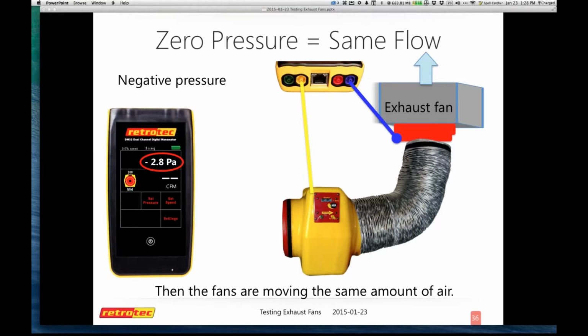John is asking, what would the tap look like inside of the flange or inside the duct? One of the methods that I use, I don't have a picture of it, maybe I may have one coming up, is I use some kind of sticky Velcro, and then I actually put the tube in, and then I put the other part of the Velcro on it. So it looks like it's closed off, but the reality is that there's enough pressure that still gets into the tube without it actually receiving direct pressure. That is one solution that works well there.